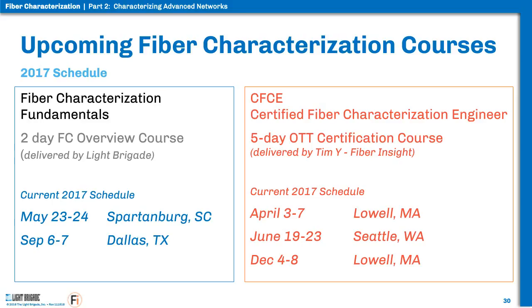So we can use the OTDR and the chromatic dispersion to clarify: if we get coefficient results that look a little strange, we can correlate that with the OTDR results showing these gainers, and do a more in-depth analysis. Based on that, you may be able to identify the sections that are G655, for instance, versus those that are G652.